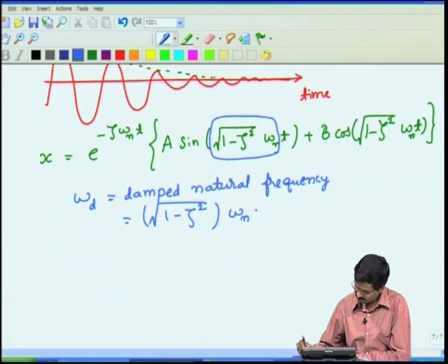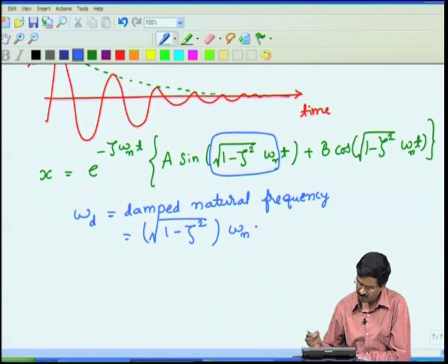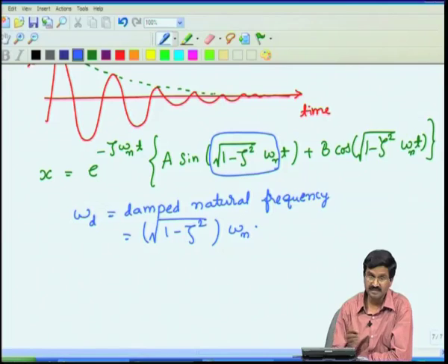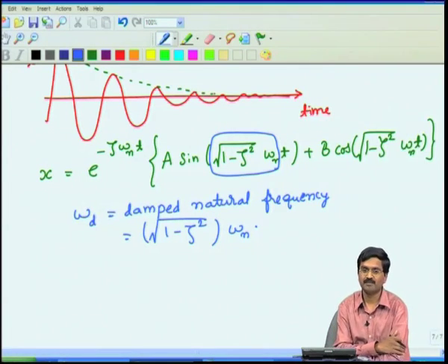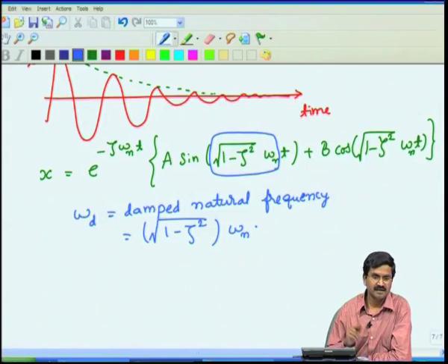Now, if we want to know what this damping coefficient is for a real system, let us say a built-in accelerometer, we will discuss that in one of the future lectures. But for now, say you do not know how to model it, but you want to know what it is. You can determine that from an experiment. If you take a microsystem device, you set the proof mass into some motion, and if you can capture that motion, you can measure the motion in various ways.